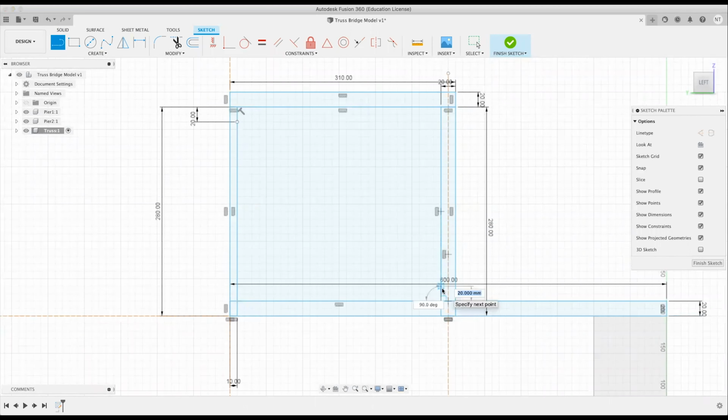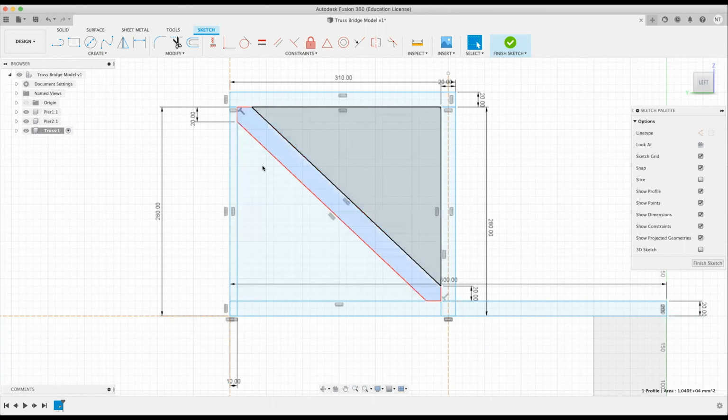And we're going to do the same thing at the bottom here, so we'll make that 20. Okay. Not sure what happened there, but it's okay. We'll click that corner, make it 20, hit X for construction line, then again, we'll go 20, X for construction line, then what we'll simply do is connect those corners. Now you can see that we have this